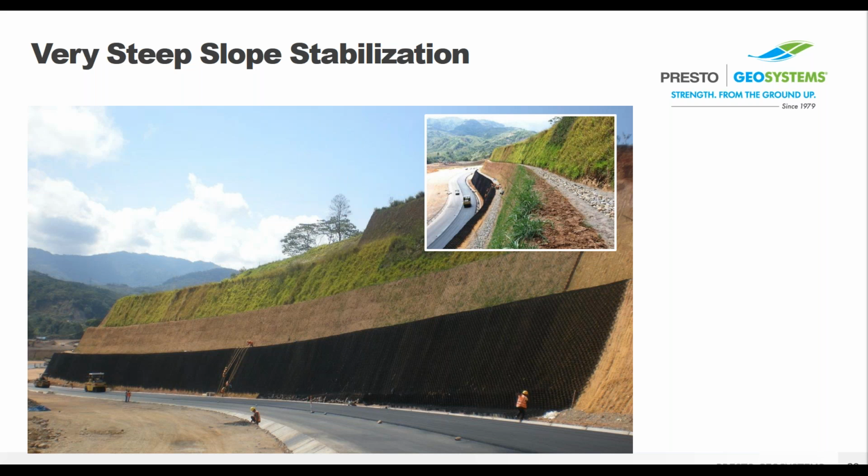These terraces were actually hand compacted at that angle, so they're not natural slopes. And because of that, they were able to confirm that each one of those terraces was globally stable in a way that a 75-degree slope normally wouldn't be. But this is why the GEOWEB Slope Protection System works, because the slopes were internally stable on their own, and they just needed that surface protection.